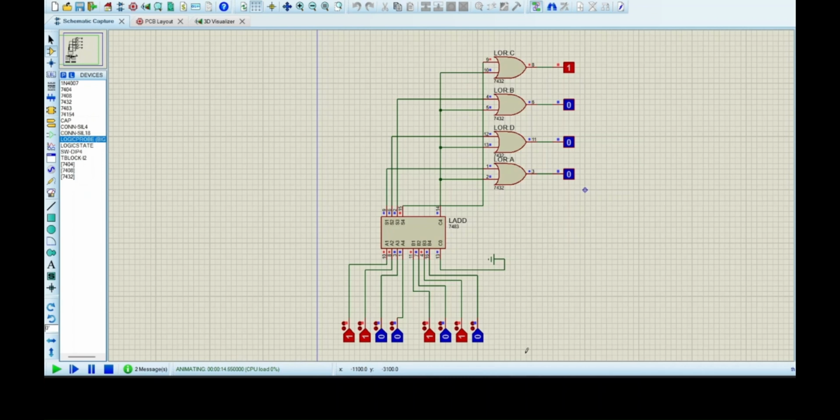Moving on to the special features. We have added the condition where the ladder top never exceeds 15. This is done by using the carry out output of the adder in the ladder module. When the sum comes greater than 15, we get a 1 output from the carry out, which is then connected to the ladder top with the OR gates. Thus, we get 111 for values which exceed more than 15.